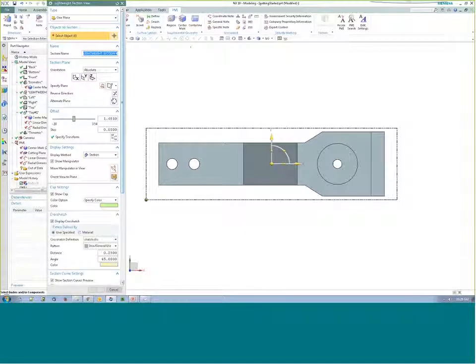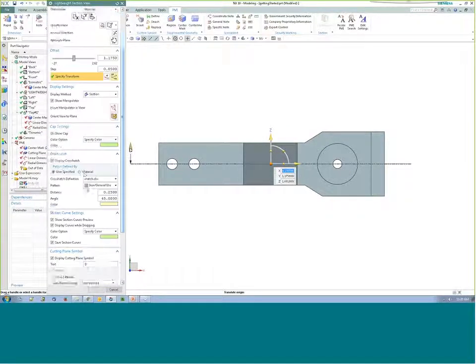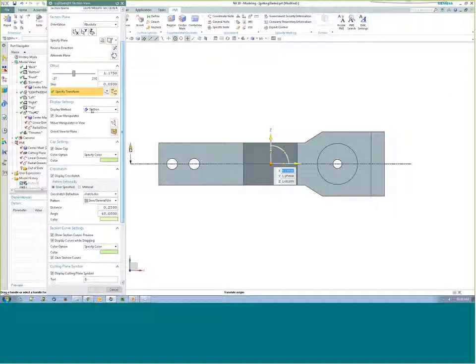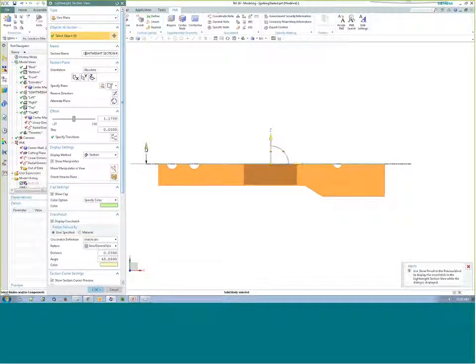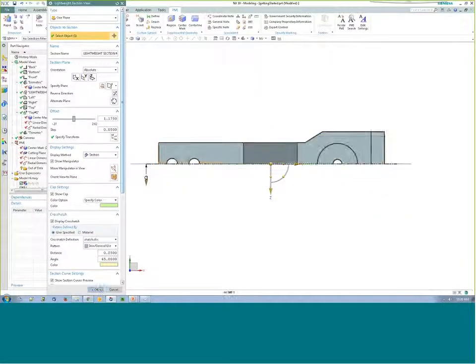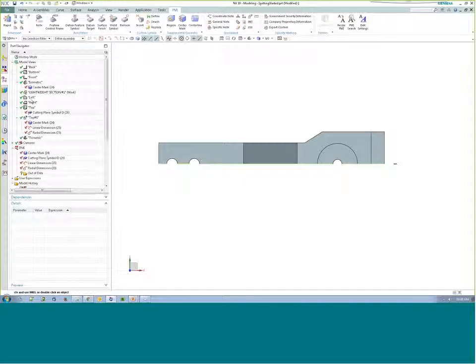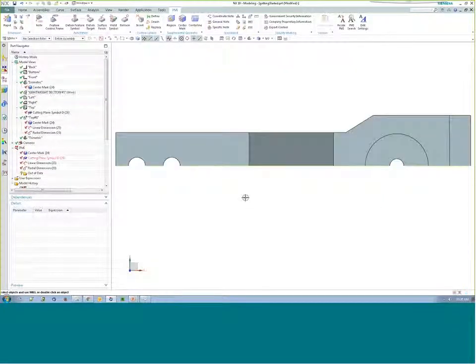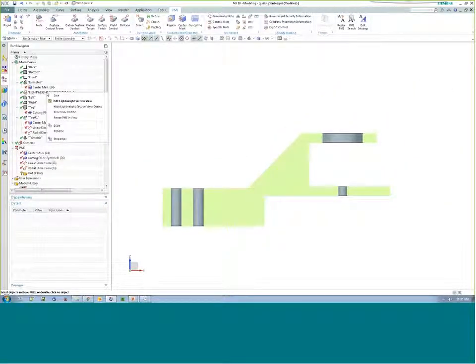it's like any kind of a section tool in NX. It allows you to choose the plane that you want it to do the cutting on and several other properties or parameters for that particular plane. And it's going to create a new section or a new model view with the name that I specify. So I choose a plane and I choose which object is going to be cut. Hit OK. And now I have this new model view. And I don't really want it oriented like this. It doesn't make sense. I want it oriented like this. So I'm going to change the orientation, right-click on that model view, and hit Save.